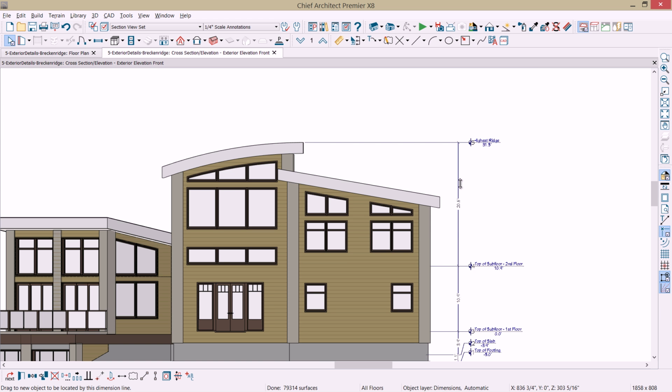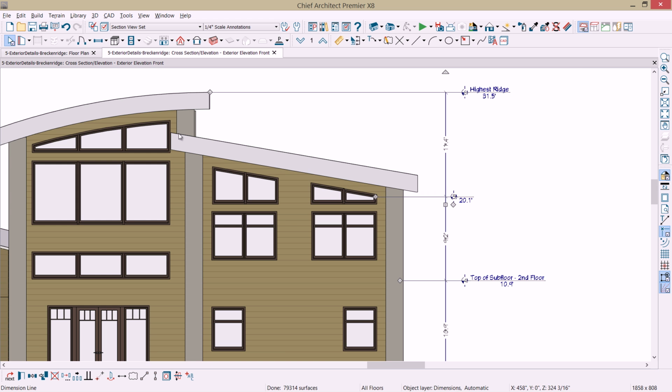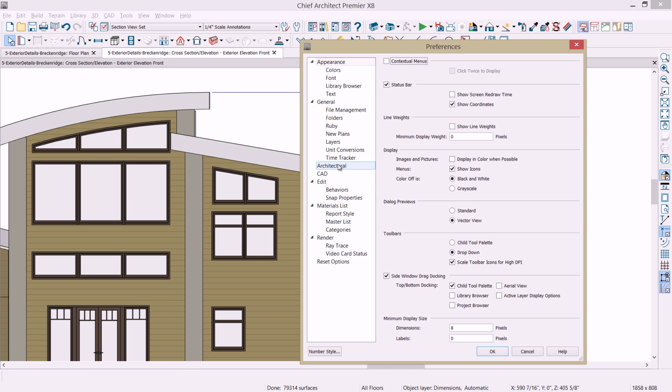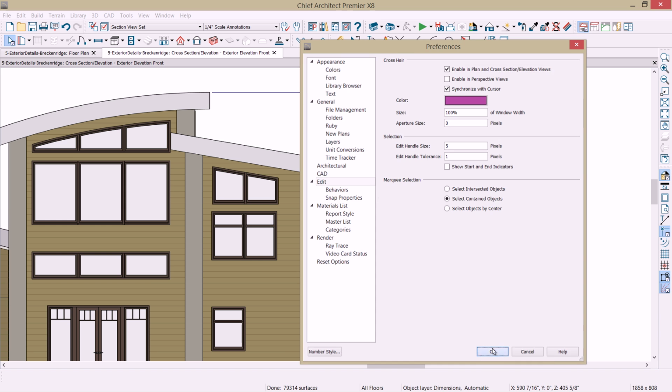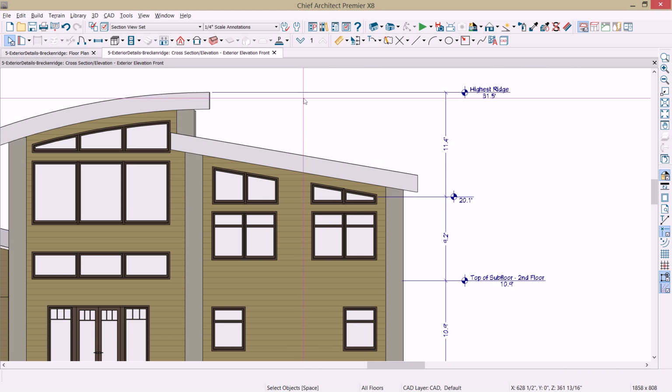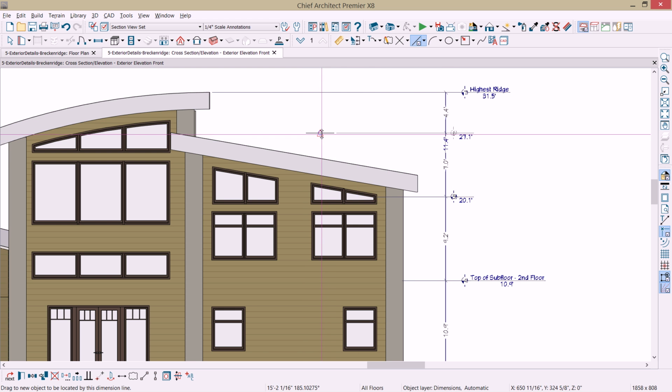Sometimes you can pick up different components if you want to pick up a ceiling or a window. In this case, I'm going to zoom in here, and let me just turn my crosshairs on briefly so I can draw a line that will show the top of our roof. So for the top of the roof segment, I'm just going to draw a line temporarily in here, and then drag that segment out onto that line. And then let's go ahead, that's extension number 6.